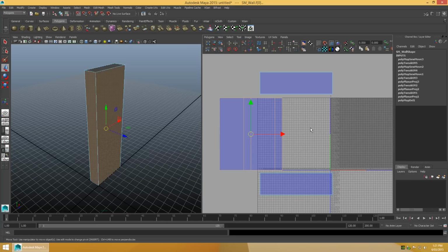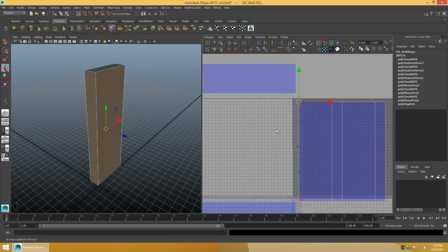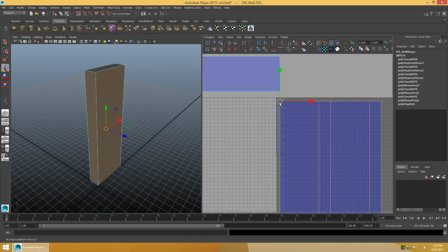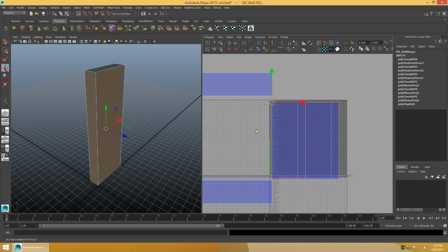Modifying the pivot point location is essential to correctly aligning the UV shells to the grid and to each other. In order to do this, toggle the manipulator between object and pivot point mode by pressing insert on the keyboard. Ensure that snap to points is enabled and drag the pivot point to the desired location. Once this is done, press insert on the keyboard once more, disable snap to points, enable snap to grid, and move the UV shell into place. I encourage you to become familiar with this process as it's used frequently when moving and scaling the UV shells.